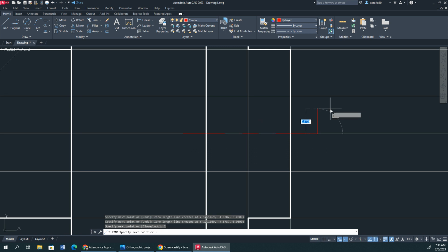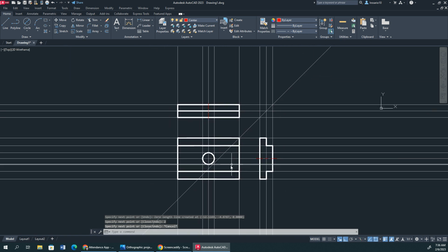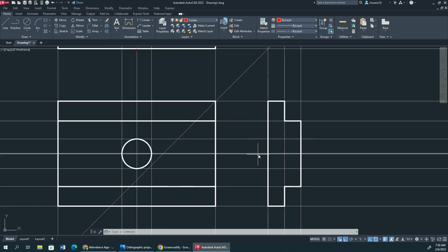Okay, so I'm just gonna type in 2. There we go. Okay. Sorry about that for the inconvenience, y'all. Usually it's pretty much easier than that, but what I did was I basically clicked line, went from here, had the object snap running tool, selected the portion right here, and typed in 2.